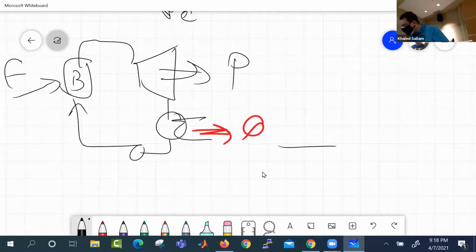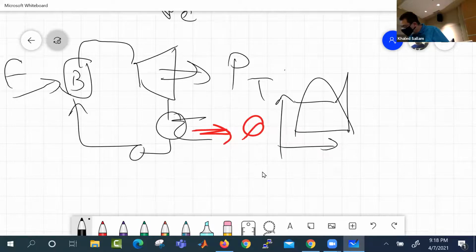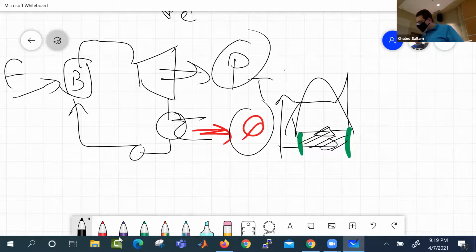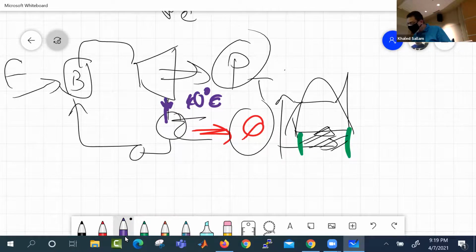So on the TS diagram, so no, not pH. On a TS diagram, that cycle would be like this. And so you would say Q rejected is basically this part, what he's dumping in the condenser, right? But sometimes this temperature is too low. It's like he's condensing at 40 degrees C or something. And he does not want to heat at 40 degrees C.